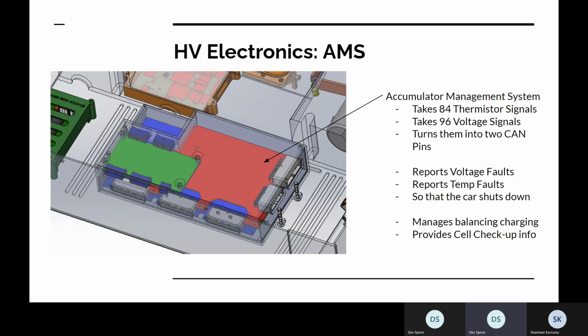If you have a basic thermistor, it's just voltage that you're analyzing via some type of microcontroller or microprocessor, so it's not necessarily slow. If the device you're using is slow, your reporting will be slow. But with a basic thermistor and a really fast sampling rate on whatever you're using, it can be really fast.